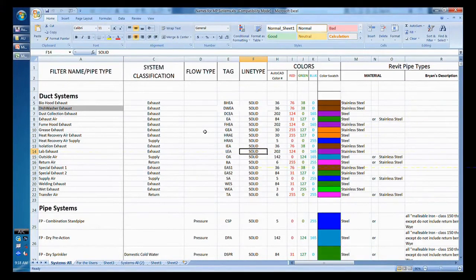Organize everything in Excel. Trying to go and start making it in Revit, certain areas will get sorted and others will not. Like the family system browser will get sorted, the filters won't, and if you start coming up with those names, it's going to become very painful as they're not being sorted, and it's going to become a big mishmash. So definitely get it started in your Excel.